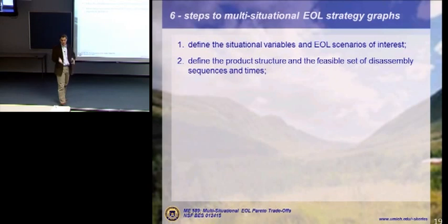So you can see that this really blows up quickly in terms of its dimensionality. So you need the product structure represented mathematically. You need the feasible set of disassembly sequences represented mathematically. And you also need to establish the disassembly times.